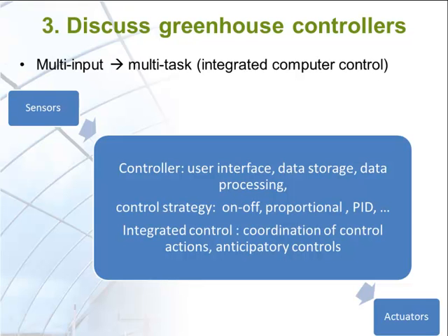This type of controller can also perform anticipatory controls that use mathematical models to predict crop growth, greenhouse climate conditions, and resource requirements. For example, precision irrigation management of when to water and how much water can be determined using water demand estimated from evapotranspiration models. Simple as well as sophisticated evapotranspiration models are available for the weather-related water demand estimation.